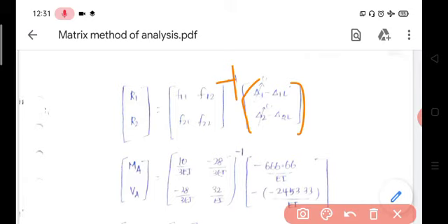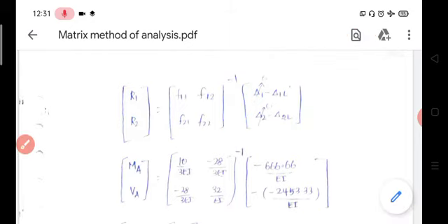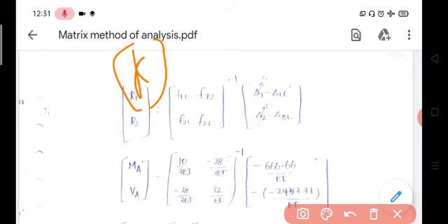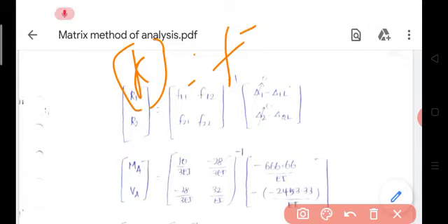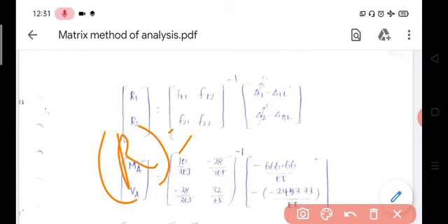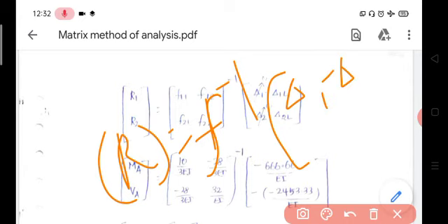So, net deflection at the coordinate 1 is equal to delta minus delta 1L, sorry, not net deflection, it is a deflection induced by the redundant force. So, use this general equation: redundant reaction is equal to flexibility inverse matrix into net deflection minus deflection induced by the external load at the assigned coordinates.